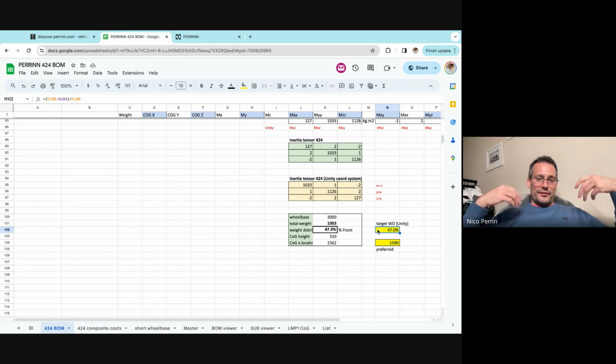Now, if you move the weight to the back, which we did, you start to get a bit more neutral or oversteer balance, and the car starts to rotate a bit better on entry in slow-speed corners. If you go too far rearwards, you start to oversteer, and the rear is just saturated. But we didn't only move the weight distribution. When we did this test, you have to readjust aerodynamic balance and various numbers. But we found that for us, 47% is the ideal number.